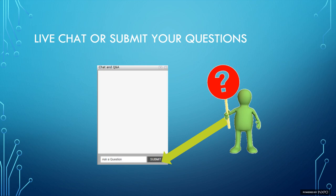So kind of related to that, if you could go over the acceptable compressor oils for food-grade applications, which ones are the acceptable compressor oils? So, okay, let's go back to the myth about oil-free compressors. Let's talk about oil-free rotary screw compressors. There's as much oil in those compressors as in a lubricated machine. It's just used for a different purpose. Instead of mixing it with the compressed air, it's simply used for lubricating the bearings and the seals, and to also do the jacket cooling on air-cooled machines.